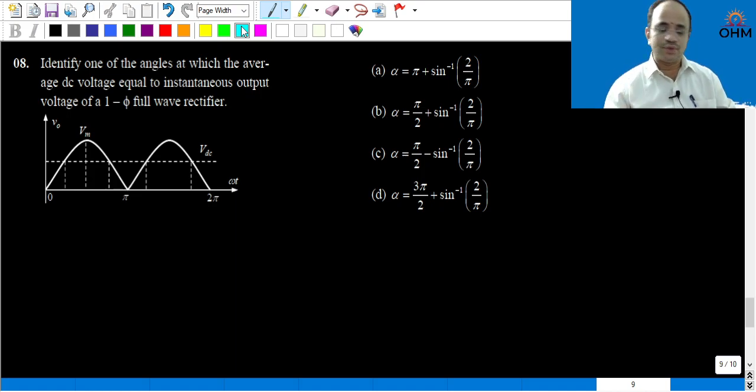Now here also students are worrying that single phase full wave rectifier means, is it a full converter, semi converter, alpha not given, diode circuit? So these type of doubts. So let us have a generalized expression. Now nothing is mentioned. Just by seeing the output voltage waveform, I can clearly say that it could be diode output, but alpha is mentioned. So I can say that diode output with alpha 0.